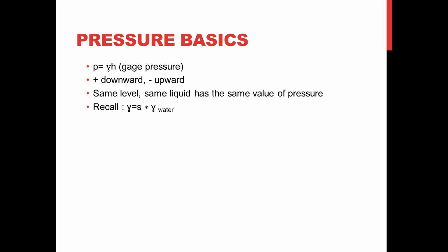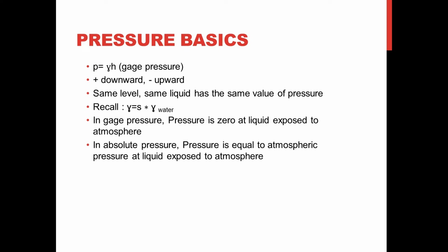We also recall that gamma is equal to the specific gravity times the unit weight of the standard substance for fluid, which is water. In gauge pressure, pressure is zero at liquid exposed to atmosphere. In absolute pressure, pressure is equal to atmospheric pressure at liquid exposed to atmosphere.